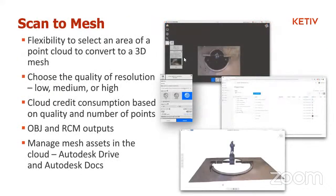So circling back to those big three I talked about a couple slides ago. Scan to mesh. This was a beta feature in ReCap previous to 2018. The process for this is very similar to how it used to be. You have your point cloud, your RCP file in ReCap Pro, and then you can select the entire point cloud, or you can select a small portion of that point cloud, and you convert it to a 3D mesh. This is done by cloud processing. So you'll pick a location on Autodesk Drive or Autodesk Construction Cloud, and it'll publish that mesh file there.